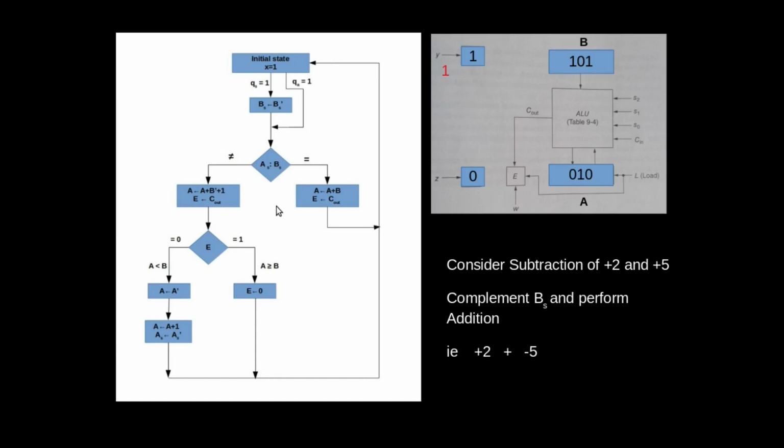So now we have to perform plus 2 and minus 5 operation. So we have reached here, AS, BS. We will check the sign bits, whether they are equal, but they are not equal. So we'll reach into this block. We have to subtract the magnitude parts A and B. Subtract B from A.